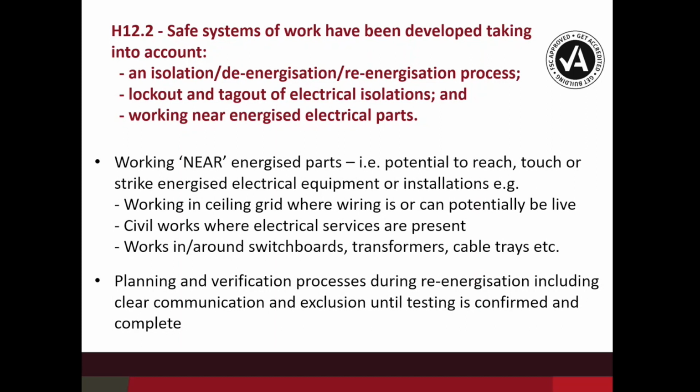This gets into the near zone, where we have a potential for a person to actually touch or disturb the electrical part. So, in other words, if I use some examples there, working in a ceiling grid where we know the wiring is or can potentially be live in some areas, typically we look for the controls to manage that process. And again, you'll see some examples of that later.